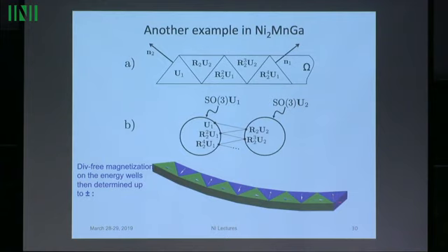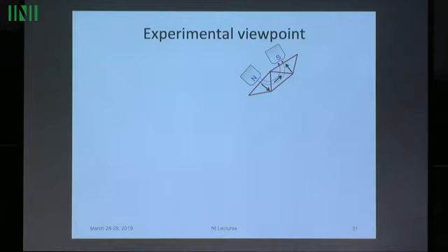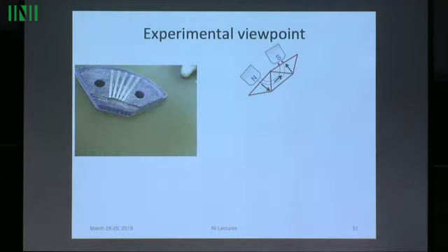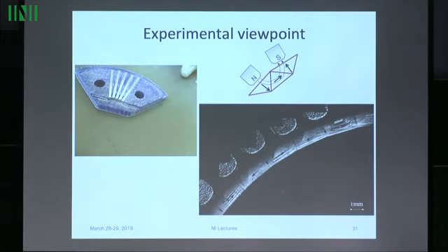It's a quite nice way to get a large bending shape by using this zigzagging across the energy wells with compatibility. But there are some poles here. There's the jump in the magnetization, dot product, the normal. There's divergence on this interface, a lot of divergence. So in fact, we had a hard time producing this microstructure till we realized what we should simply do is put little magnets there and get rid of the poles. And so we made a little device like that. And then sure enough, we saw those nice triangles like that.